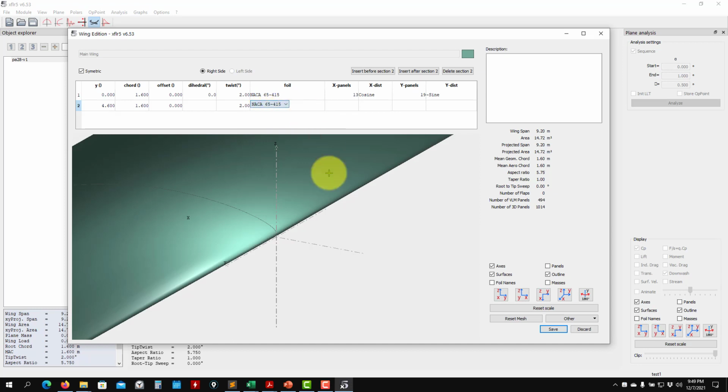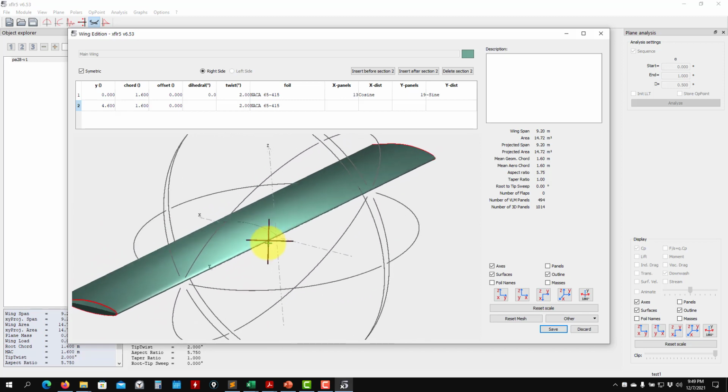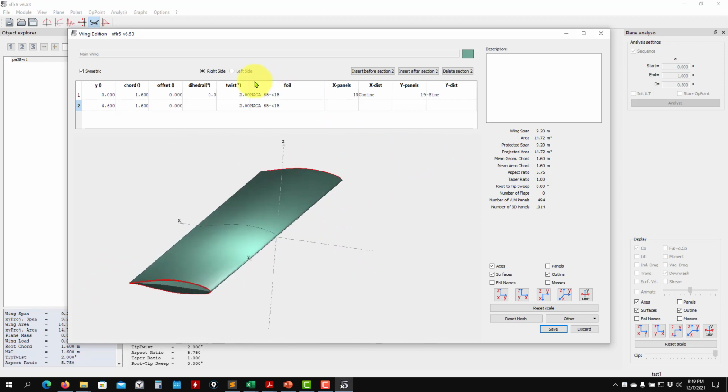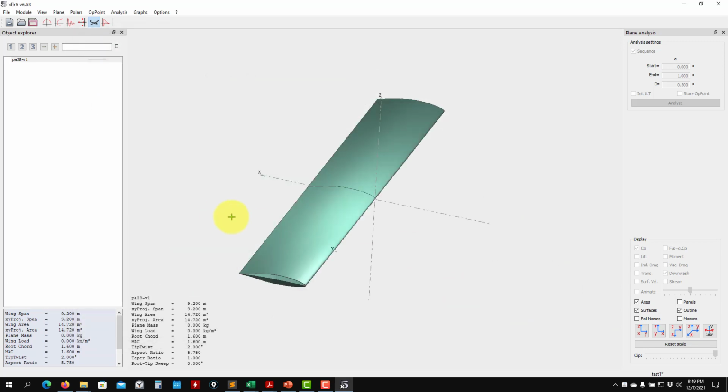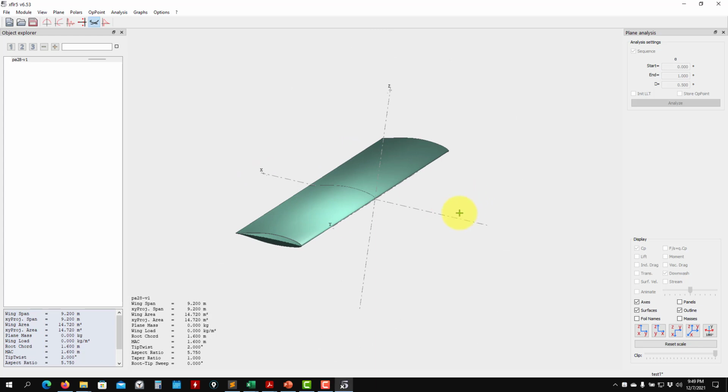So later I'm going to show you all of that. See that now you put the airfoil, and this is your actual wing. When you load this airfoil, automatically you are loading the information that you have there, the polars at that Reynolds number, all those polars, okay? So that we have that, we save, and at this point we're ready to go, okay?